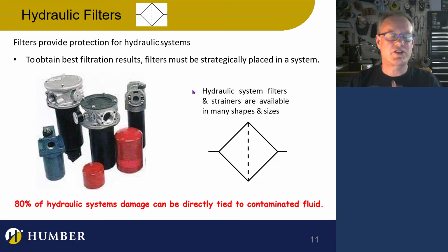So that's a story about a gearbox. The best way to make sure that gearbox is well maintained, and the bearings are always going to work and not run out, is to keep the oil clean. Otherwise you can get vibrations in there and some real damage can occur to a gearbox with dirty oil. It's just, clean the oil.